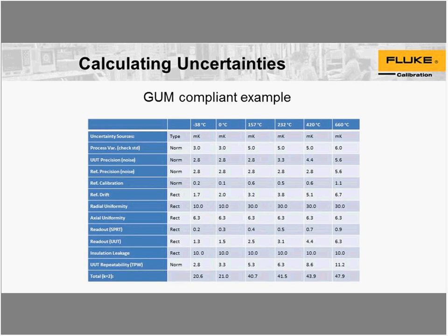But you'll also notice here, not just using a plus/minus uncertainty, they're actually breaking it down into a K equals 2 of all of the various pieces. The K equals 2 is more or less a 95% confidence that if I make a measurement at, say, 0, I'm going to have an uncertainty. In this case, I think most folks will work in milli-K, so it's not 21, it's 0.021 milli-K, or you're equating that to a plus/minus 0.021 C uncertainty for that particular temperature using this setup.